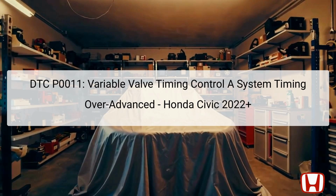The diagnostic trouble code DTC P0011 indicates an issue with the variable valve timing control (VTC) A system. This particular code suggests that the timing for the intake camshaft phase angle is set higher than the intended or commanded value, which can lead to performance problems. The Powertrain Control Module, PCM, identifies this abnormal condition and records the DTC.